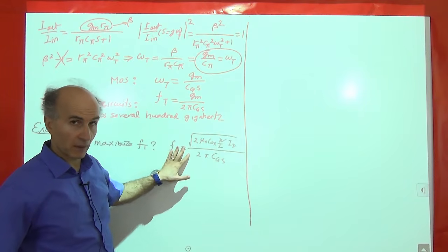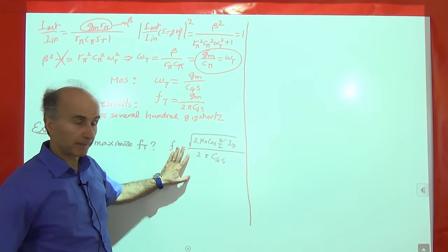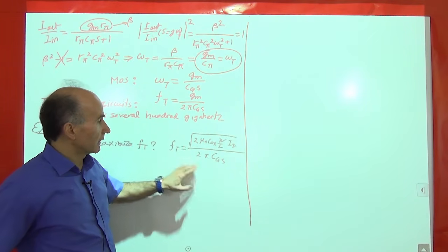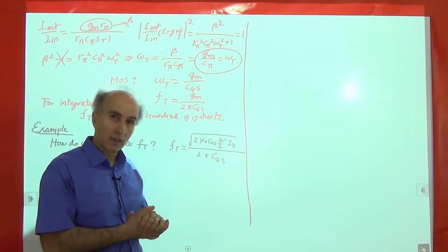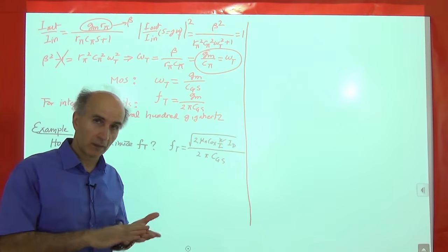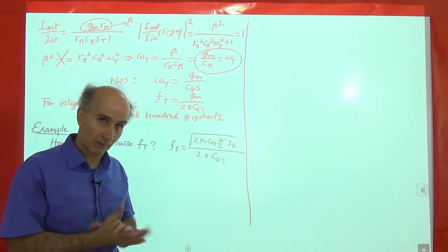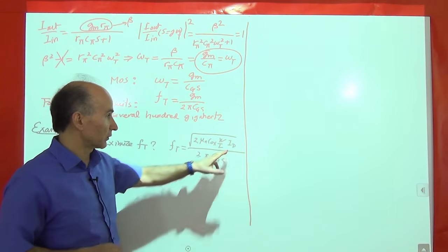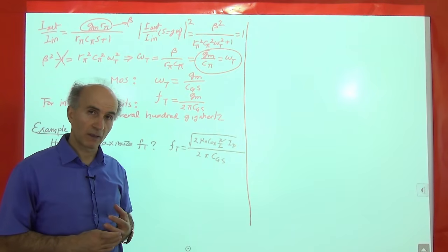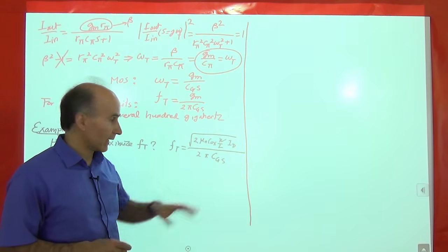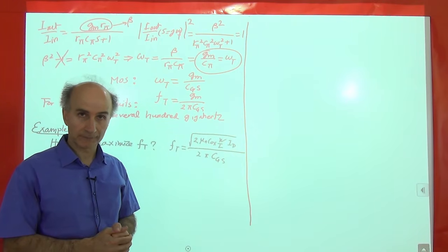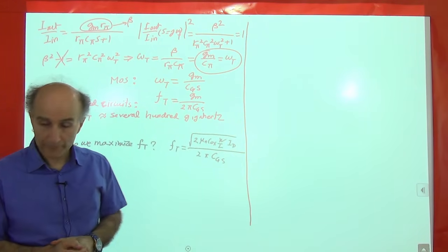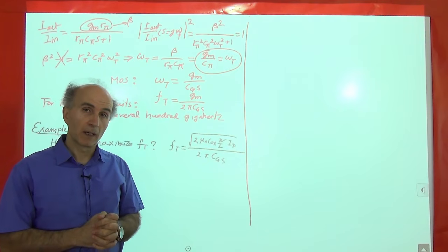This is for MOSFETs, not for bipolar devices. So that's one technique that we try to use. Of course, there are trade-offs in that. As usual, we have a trade-off between speed and power consumption and gain and everything else. But that's something that we could try to do by maximizing the drain current so that CGS is constant. We can just keep increasing VGS and the current. Okay, this concludes this lecture. I will see you next time.